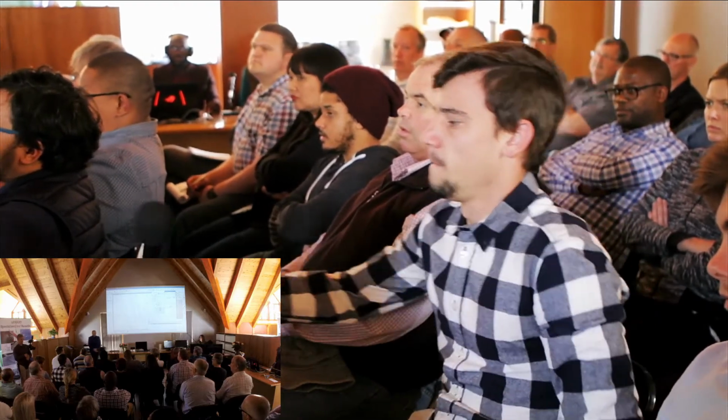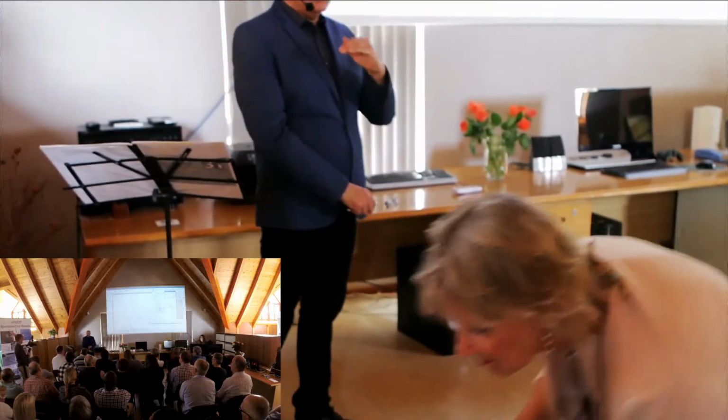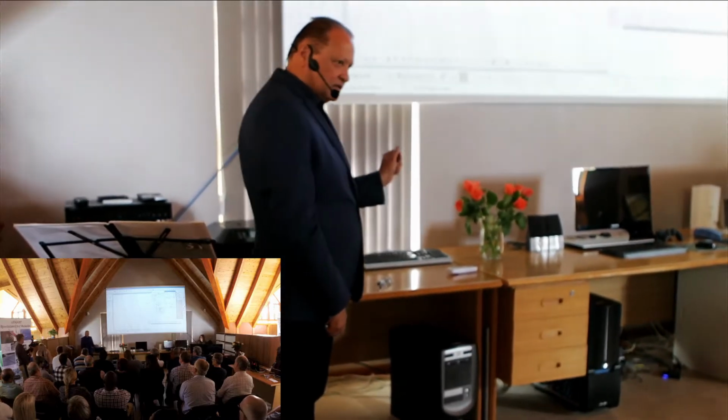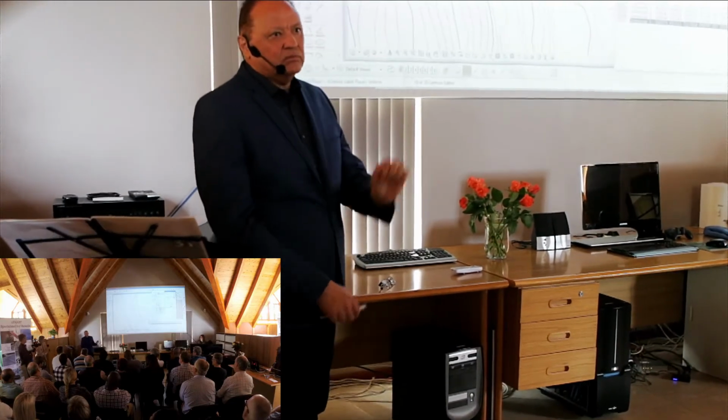Regarding the movement on your contours, you're moving the XY position. Does this affect the Z? Because on your triangles, your Z is going to be different from the contour that you just moved. So how do we get an accurate result? It's not linked to the triangles. It picks up the height of the contour, knows the height of the contour, and it will hold it at that height. So if you're moving a contour at 100, it's going to stay at 100 and insert.